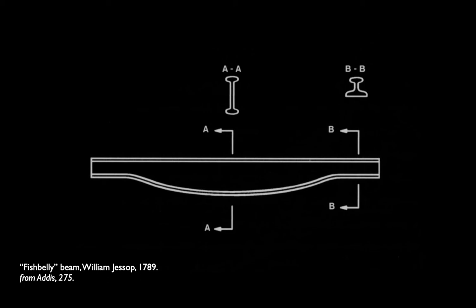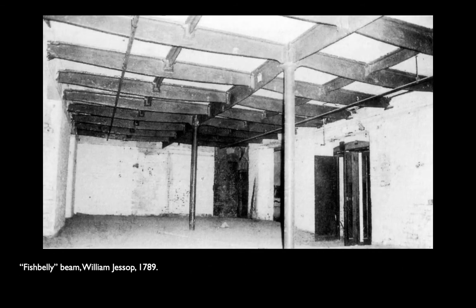Right? Put a flange on the top and the bottom of the beam. You draw the resisting moment out to the greatest moment arm you possibly can. Increase that moment of inertia, increase that section modulus, and pretty soon you have a really modern I-beam.